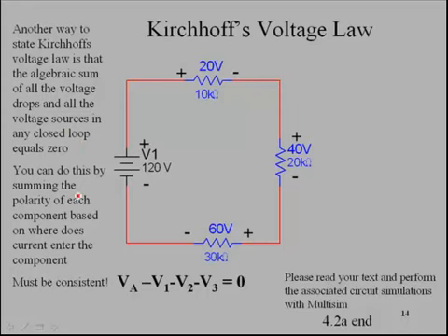And you can do this by summing the polarity of each component based on where current enters the component. And so if we look at this and we think, well, current is flowing in this direction, and we're going to evaluate the polarity based on where current enters that specific component. So if we start at this point right here, the polarity where current enters the power supply is positive.